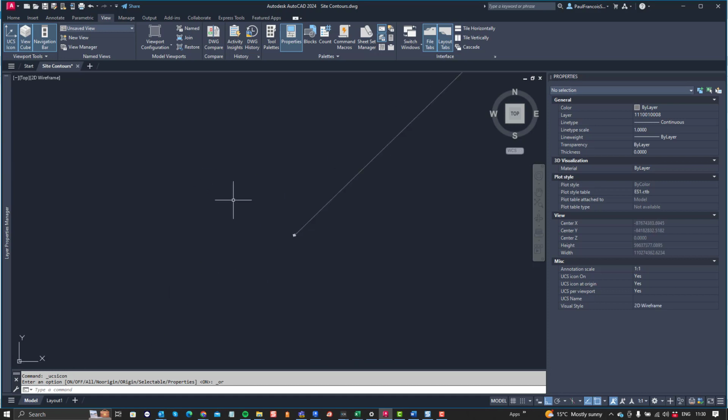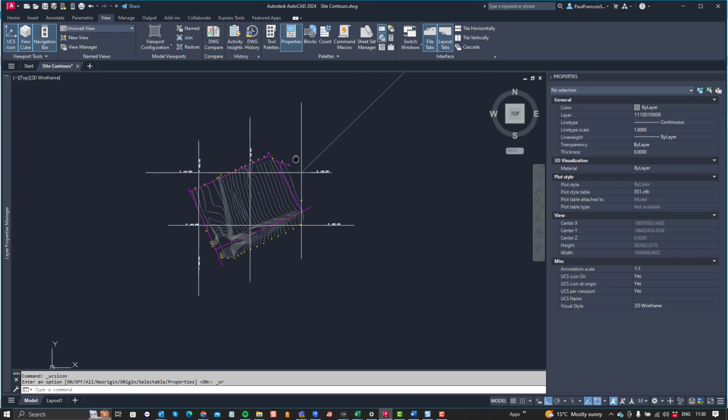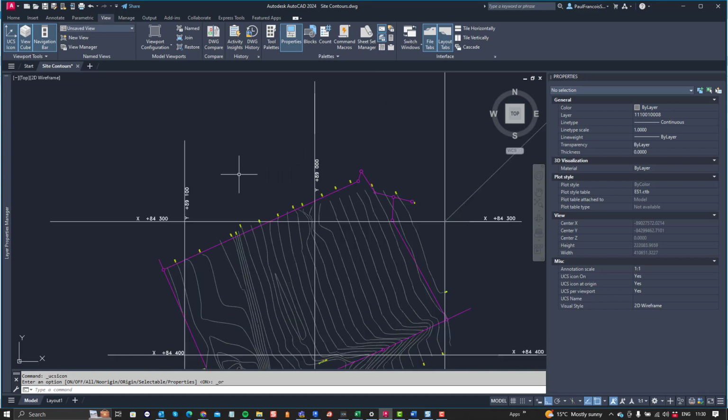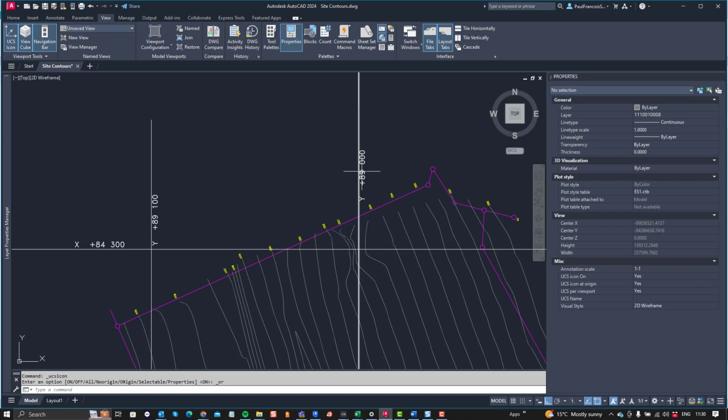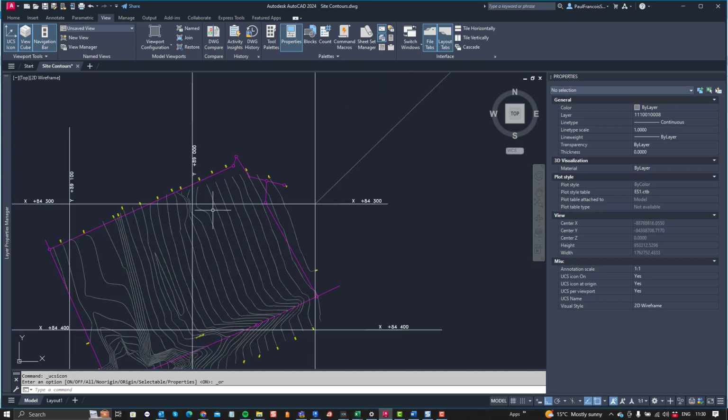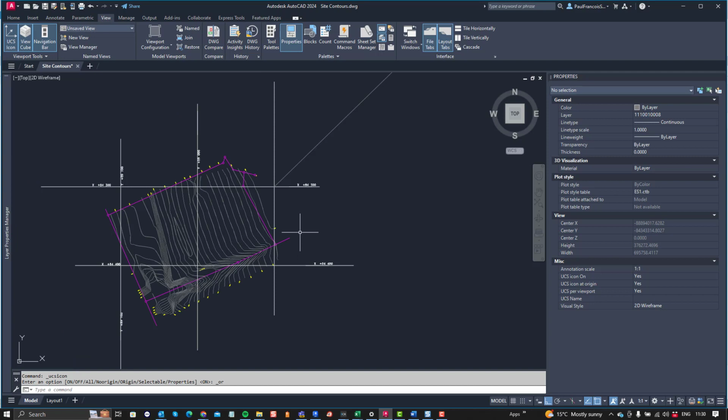Now the result of this is you have to look at the increasing numbers on a southern hemisphere or on a South African survey that looks like this, where it goes from 89 to 89,100, and then recognize that it's increasing positively in the negative direction as our axes are defined at the moment. So X is positive towards the right, but we are now saying that it's going towards the left, increasing positive, and so we have to put this in the negative quadrant. Similarly in the Y direction as well.